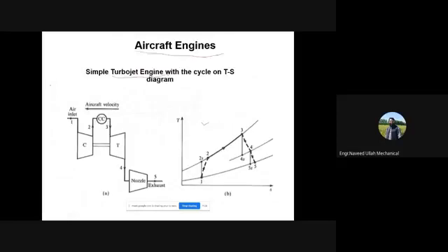this one. If you look at the flow diagram, what happens is that the air comes to the compressor and it is compressed, right? And it is then given to the combustion chamber as we discussed earlier. And the air at state 3 is here, okay? So the enthalpy is basically changed from H1 to H3, right? And then the enthalpy drop, okay, or this decrease in enthalpy, that is your H3 minus H4. This is the useful work produced by this turbine, okay.